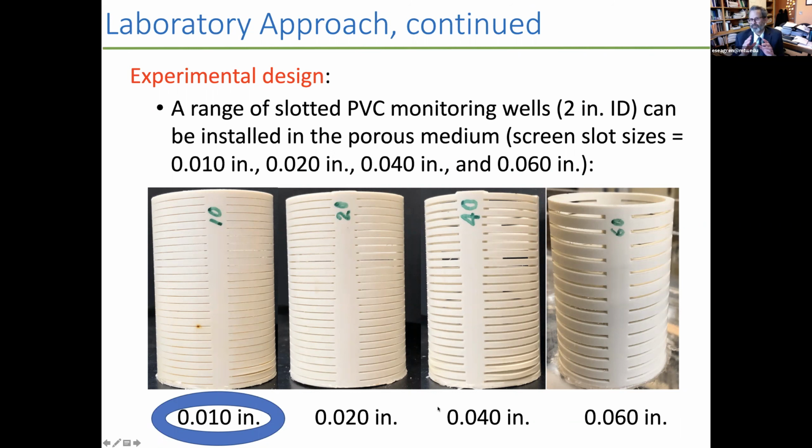Of course, there are many different well screen designs we could have used in terms of slots, but in this way we had the same type of well, only changing the slot size. So we looked at 0.01 inch slots and 0.02 inch slots, which would be more typical monitoring well sizes, and then 0.04 and 0.06 inch slot sizes, all 2-inch internal diameter.